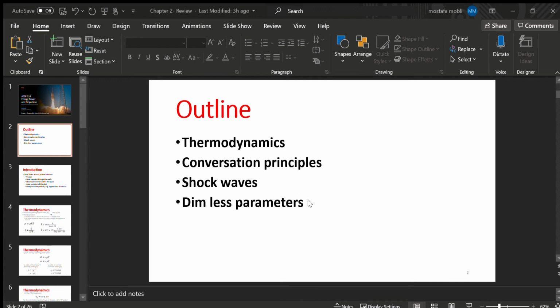Okay. So whatever change of momentum you have inside a control volume over time, right? The rate of change of momentum over time is going to be equal to the total of forces being applied to it. Mostly in the fluid case, it's just weight, right? But in propulsion case, we don't have that weight as well. Air is assumed to be weightless. And the changes of momentum on the surfaces of that control volume. So it's essentially the fluxes of force coming in as well. Okay?